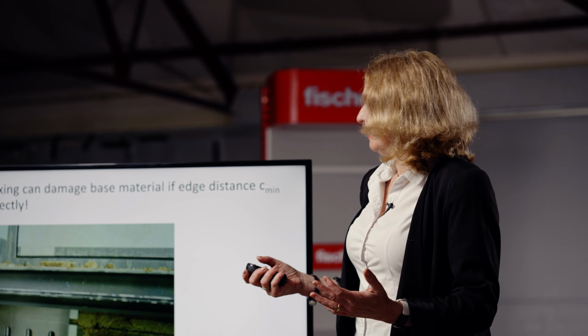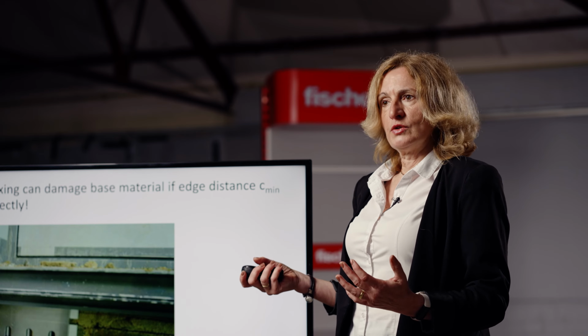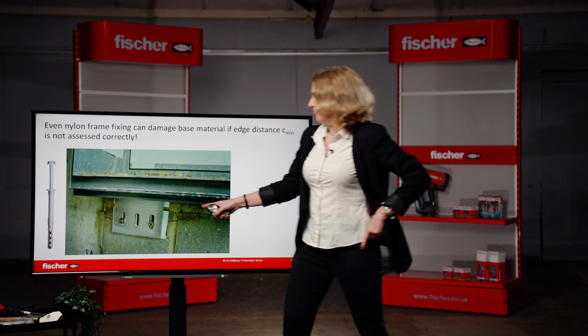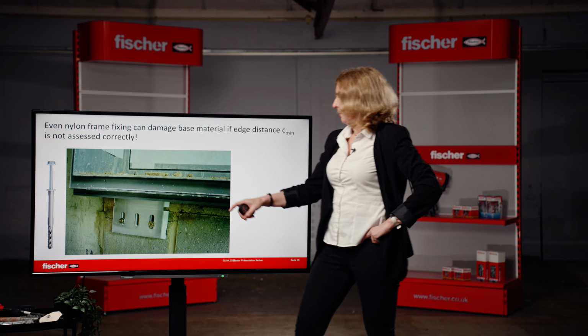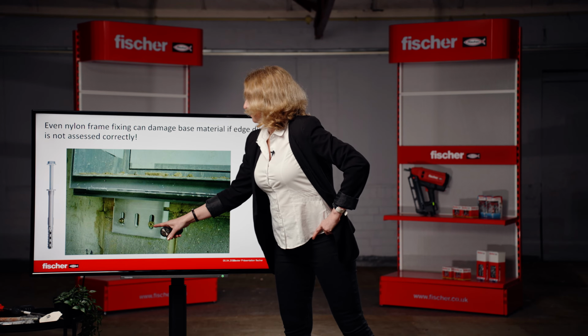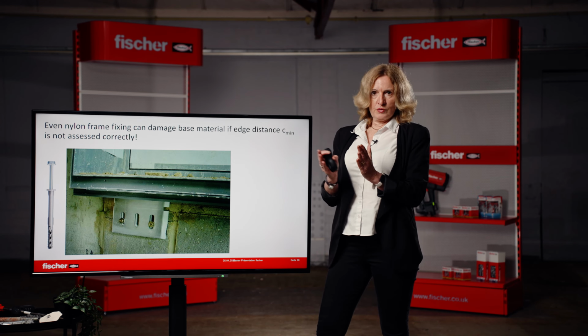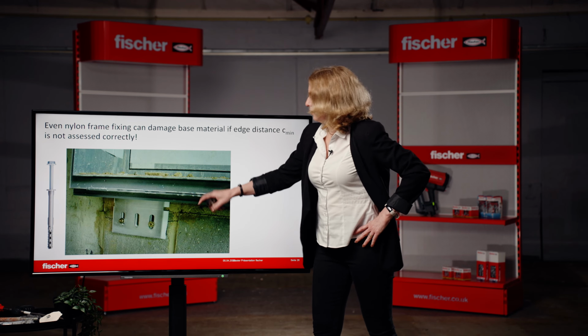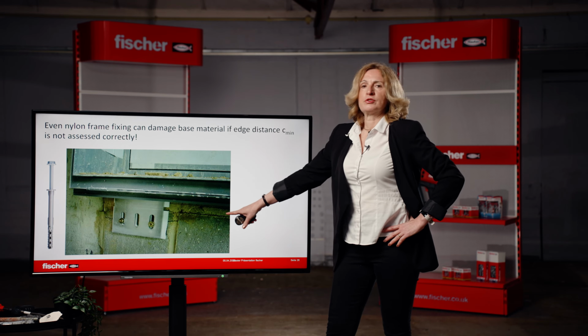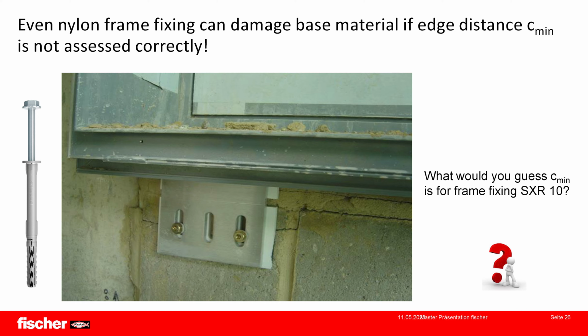And even nylon fixing can cause damage. Here we see the connection of a large window and 2 nylon anchors installed in close proximity, close to a free edge, and you see the damage to the substrate.